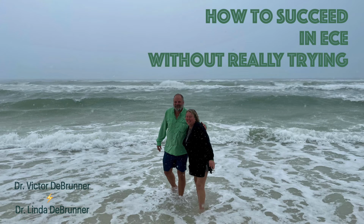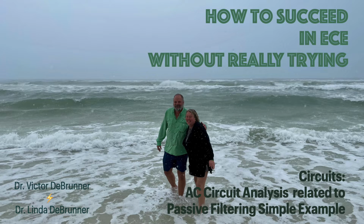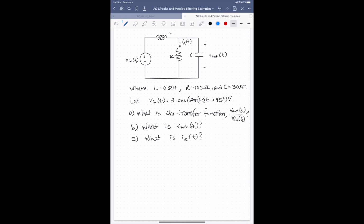I'm Dr. Linda DeBrunner, and in this video I will talk about how to analyze an AC circuit using techniques from passive filtering. We will do a simple example. What we'd like to do here is calculate the transfer function V out of S over Vn of S, and then we will solve for a particular V out of t given the input Vn of t is equal to 3 cosine 2 pi 60 t plus 45 degrees.